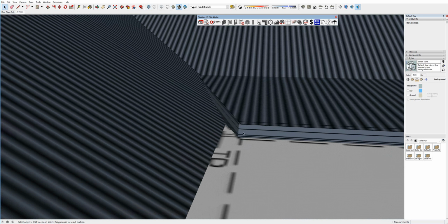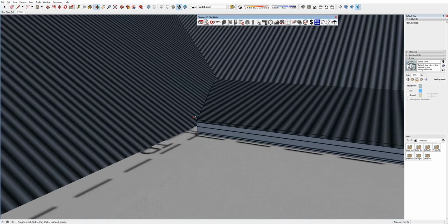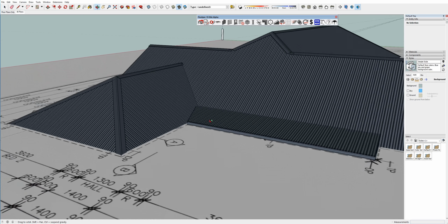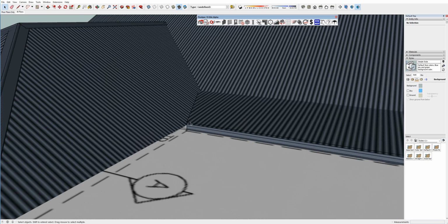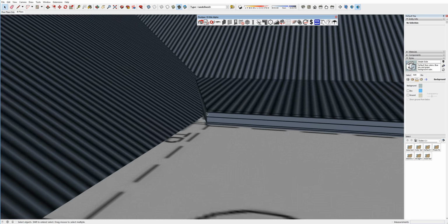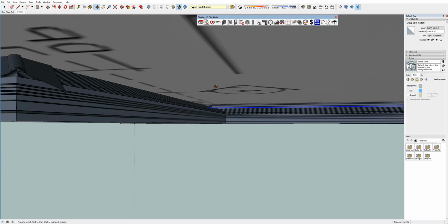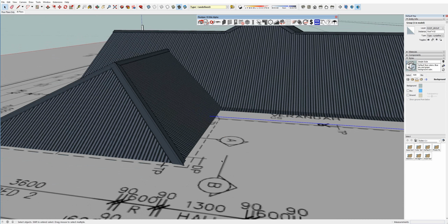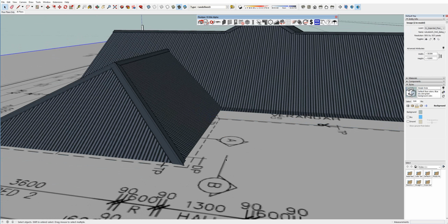You can see that I've missed that. I should have come over a little bit further. It just means that the plan's out, or the pitch, which I didn't know what it was. I guess 5 degrees. It could have been whatever. And essentially I want to move this down so that it lines up with my fascia height. There. And I have what I need for drafting purposes.